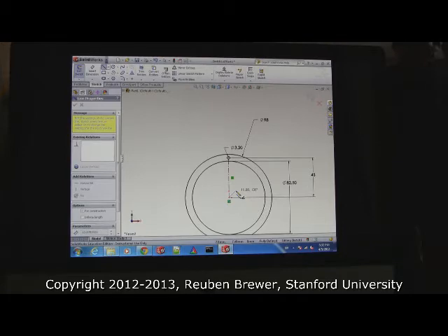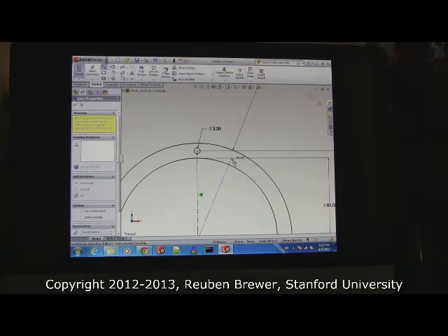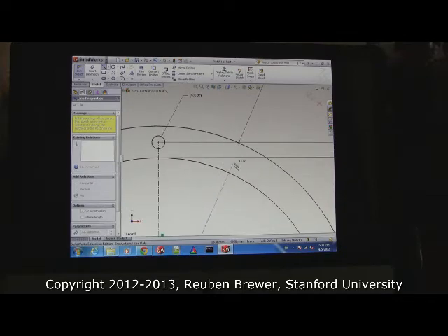Okay, does everyone's screen look like mine? Take the line. Oh, there's one more angle it will snap to, which is 45 degrees. We're not doing that. So take the line, and I want you to zoom in before you place the second end, so it doesn't snap to anything randomly. Look at my screen. This is about how you should be doing it. And just place it somewhere in between the two circles, maybe about a 15 degree angle so it doesn't snap to anything weird.